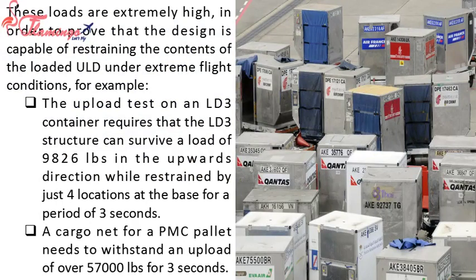For example, the upload test on an LD3 container requires that the LD3 structure can survive a load of 9,826 pounds in the upwards direction while restrained by just 4 locations at the base for a period of 3 seconds. A cargo net for a PMC pallet needs to withstand an upload of over 57,000 pounds for 3 seconds.